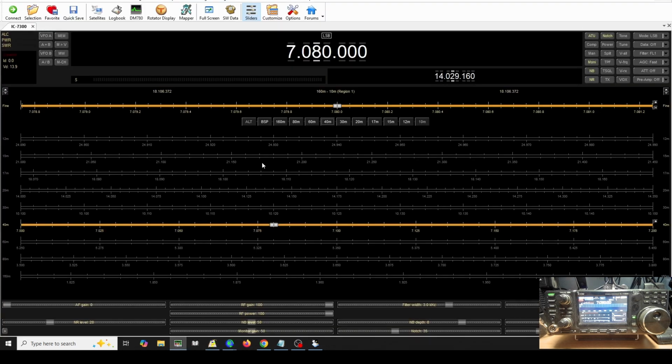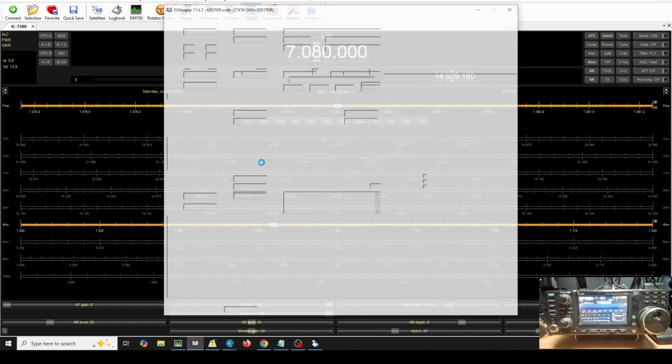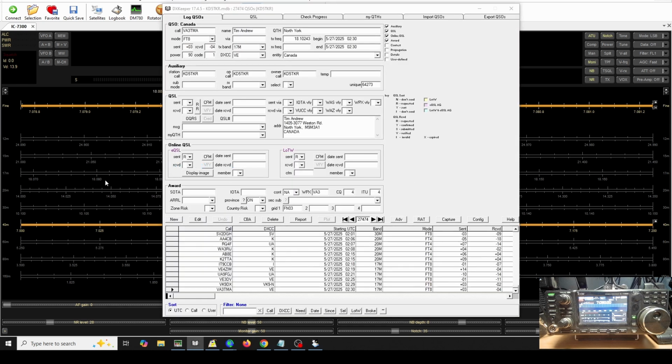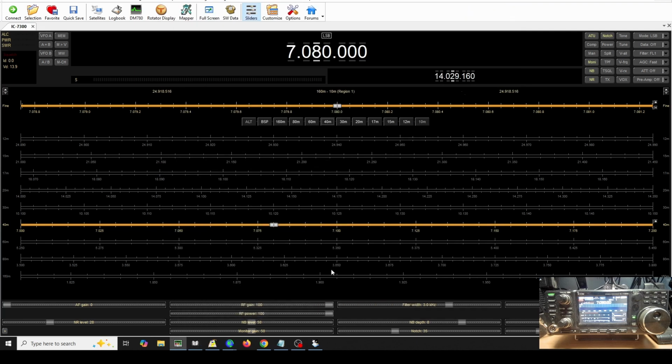I'm also running Ham Radio Deluxe. Now, Ham Radio Deluxe is what I use to interface WSJTX to the radio. And the reason I do that is that when I'm operating remotely, I can remotely control my screen and control my RF power. So if I want to be at 10 watts, I can set that. If I want to be at 20 watts, I can set that. 30 watts. You see how it works. If you just use WSJTX directly, there's no facility to control power other than adjusting your audio drive, which has its own issues. So that is how I do that.